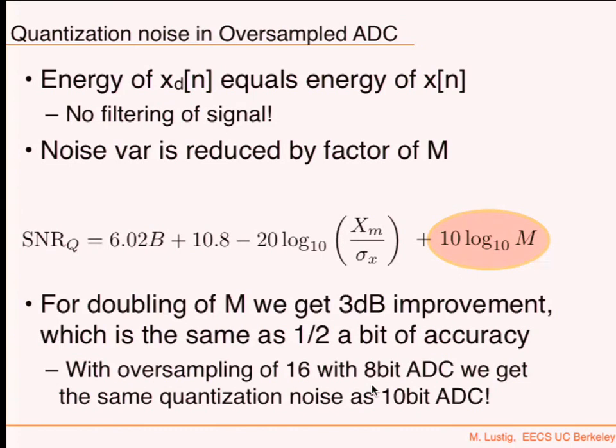And if you want a quarter, then you turn the voltage on for a quarter of the time and then off for 3/4 of the time. If you put a low-pass filter after that, you get an okay digital to analog converter. This is the opposite, where you have some voltage changing in and then you quantize it to either 0 or 1. It's exactly the opposite. Then you can filter it digitally. Okay?